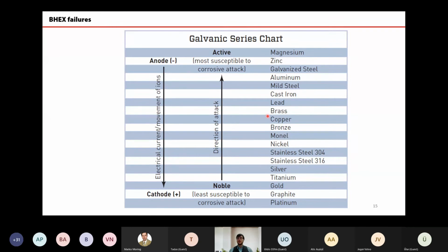As soon as you have anything which conducts electricity touching stainless steel and copper, it starts corroding immediately. The speed of this corrosion will depend on the electrical conductivity of your water. So that means in the most general case, we will have a very challenging situation for the copper brazing material on the side where you have your cold water, which turns out to be hot water.